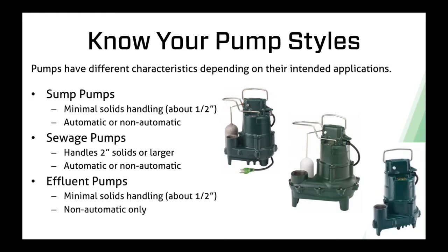And lastly, we'll talk about effluent pumps. Effluent pumps are similar to sump pumps in many ways. In fact, they share a lot of the same models. An effluent pump that's pumping the liquid that comes out of a septic tank, that liquid should not have solids, and so the effluent pumps that we have really aren't designed to move larger solids. They would get clogged up easily if you were to put them in a solids-heavy environment. The difference from a sump pump, however, is that we do not want to use an automatic pump in that application. We really want to deal with non-automatic pumps only.